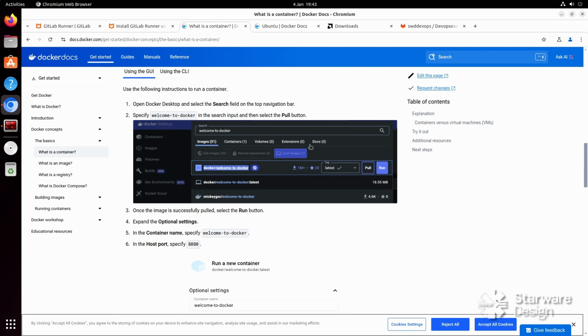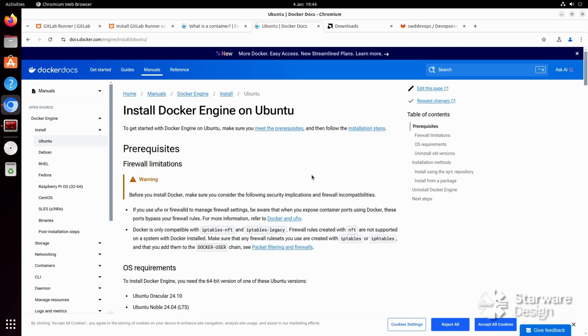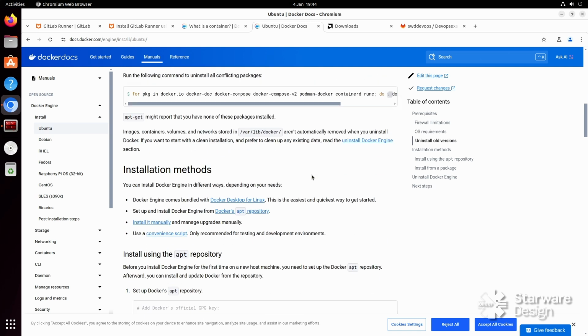out as one package. Container image is described by a file, Docker file, which contains a sequence of commands to create the image itself, packages to install, configuration, is all you need to replicate the exact build environment on another machine. The objective is to create a container that will run Vivado without user interface to build the FPGA bitstream and Petalinux to build the Linux image.